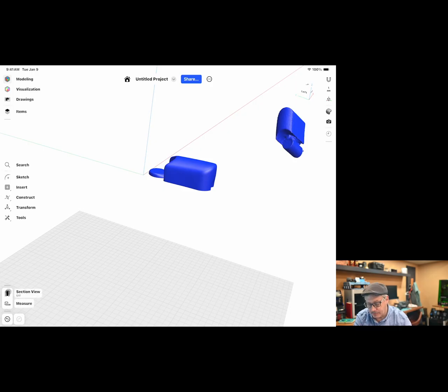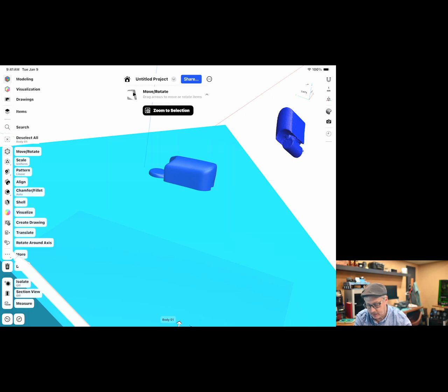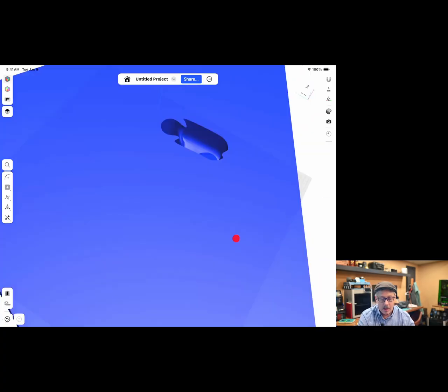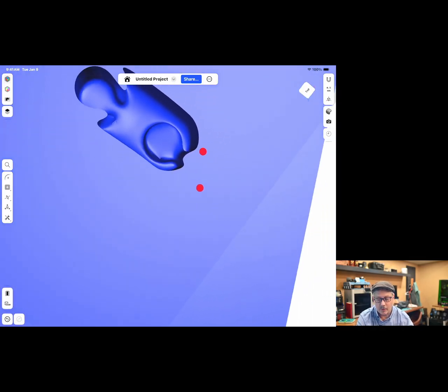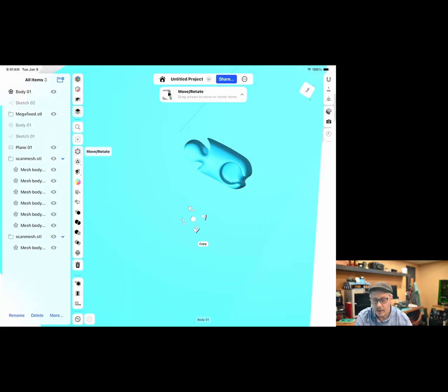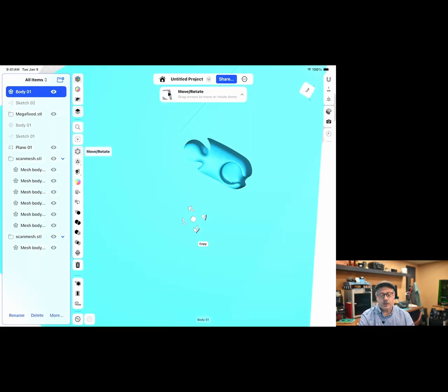And what happens? Oh, I didn't want to do a subtract. Gosh darn it. Back. This guy, I want it to subtract that guy. And you think, oh, look at that, I've got something I can work with. Well, you don't, because it converted the first mesh body you had, and it took the nice step file, the nice Shaper file, and turned it into a mesh. See how it looks like a star? So you took your mesh into a perfect CAD file, and by trying to trick it, now you have multiple meshes on your hands, which doesn't solve anything.